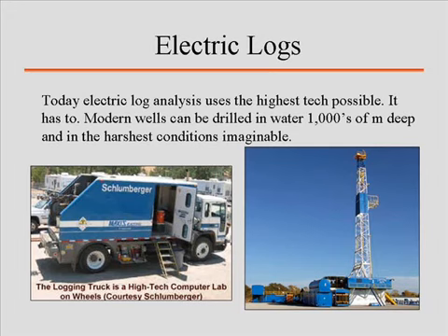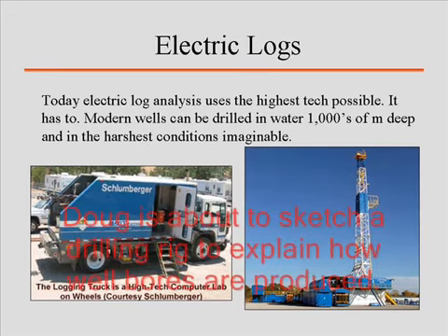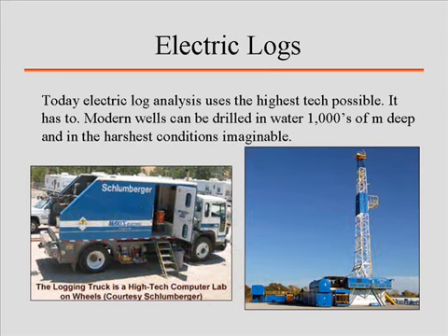And you all know how these things work? I actually haven't told you anything about it. All right. Well, basically, they have a rotating platform at the bottom here. That's where most of this is diesel engines to run the turret. Okay, so it turns. It's got a clamping device that clamps, and as it's turning, it's forcibly causing the drill pipe with the bit on the end to turn. They add drill pipe to the top here. There's a little crane off the side where they can actually grab stacks of pipe, bring it over here, load it up. That's what the roughnecks do.